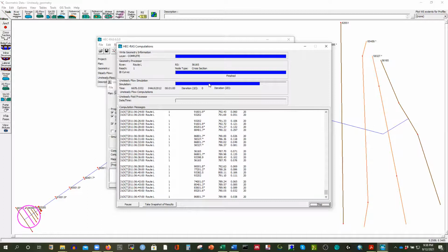But for other cases, maybe it is useful if you have a natural canal or channel and you need to optimize, because these are basically prismatic canals, the regular shape of the canal, right? It is artificially constructed, so we call it a prismatic canal. And if it is non-prismatic, meaning a natural canal, then you need to use even that minimum time step for your model to be stable. So we have to test this time step. That's why I'm going to show you this one, because we'll use different time steps for sediment transport analysis in order to make the model stable.